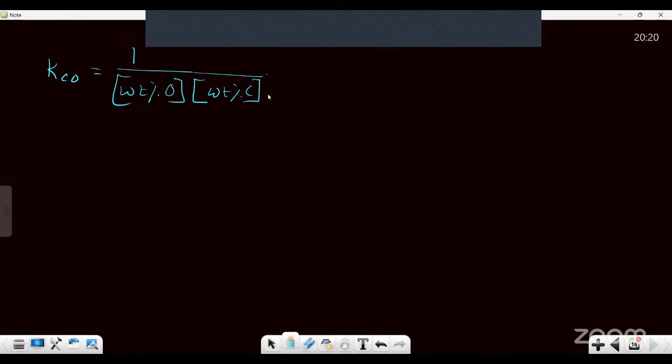Now, this tells us that at equilibrium, if temperature is given to us and the pressure is constant, so temperature is 1600 degrees Celsius, right? And we are maintaining the pressure constant, 1 atmosphere. Then the weight percentage of oxygen into the weight percentage of carbon is constant.